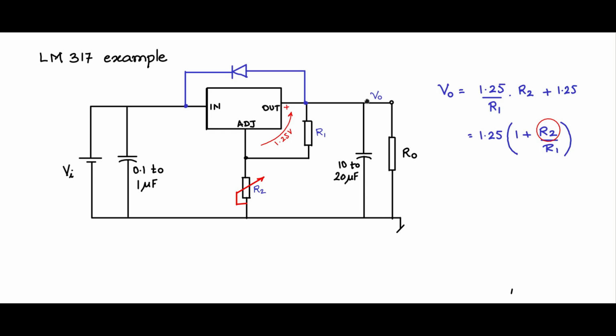Now, when you switch off, let us say the input goes to 0 quickly and the output has not yet discharged, which means the out terminal will have some finite positive voltage, the in terminal will be 0, and then the input to output differential voltage will be negative, which will damage the IC.